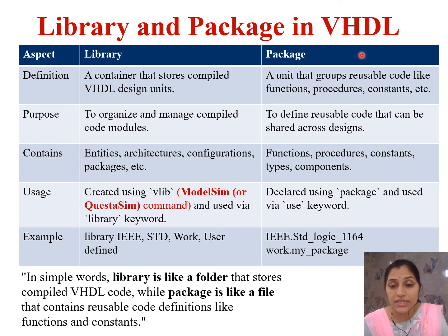Whereas the examples of packages are: this package belongs to library IEEE. So IEEE dot package name is std_logic_1164. Then work dot my_package.